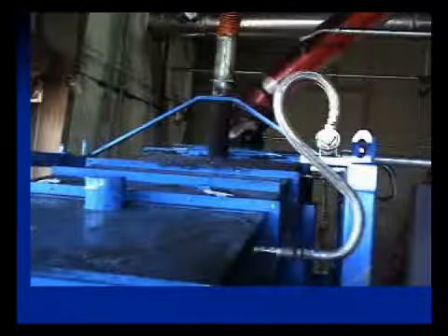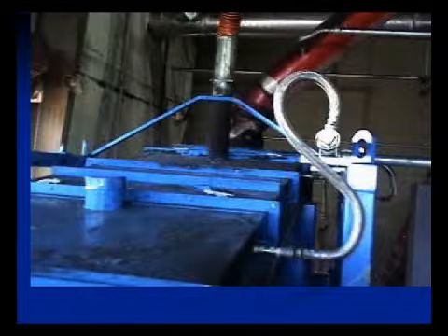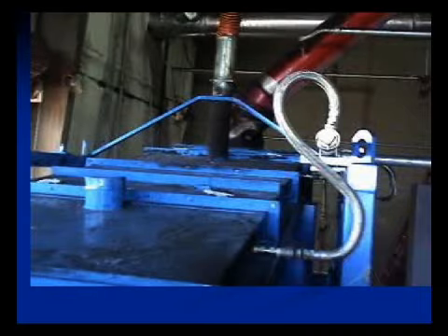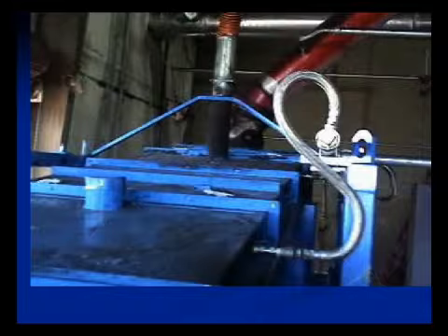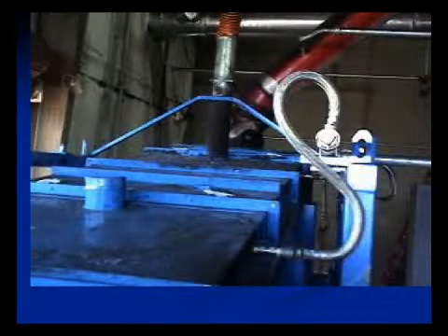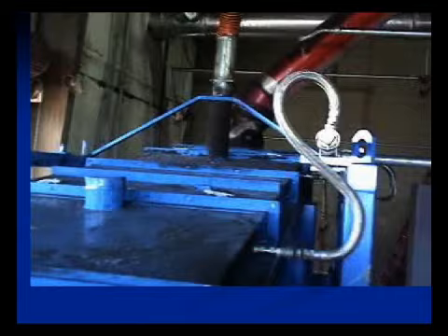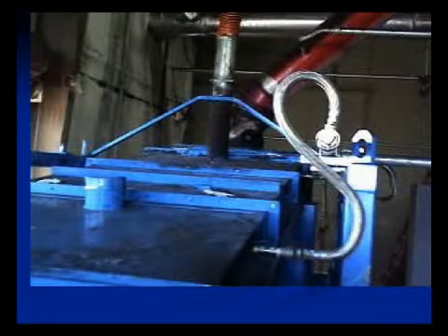In this stage, the shattered rubber, which is separated from fiber and steel, goes through a classification unit. In this stage, you're looking at separating the fiber and steel from rubber. If you notice, we have these nozzles. These are the fire nozzles. Our fire suppression system is a computerized system. We have smoke detectors, we have heat detectors, and if any of the detectors see anything, it would open up the water to the system.